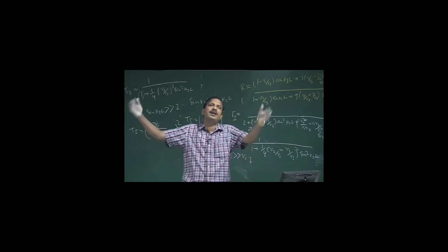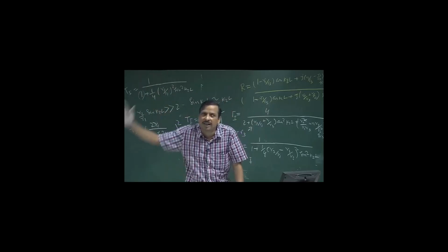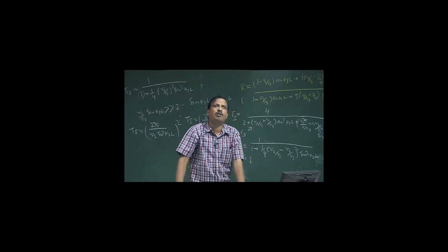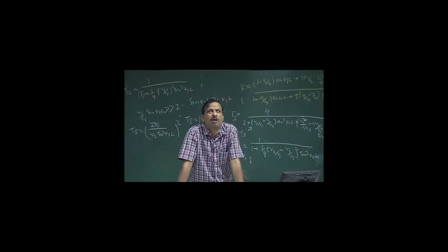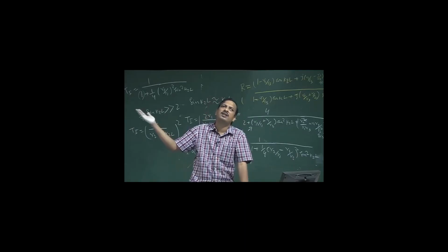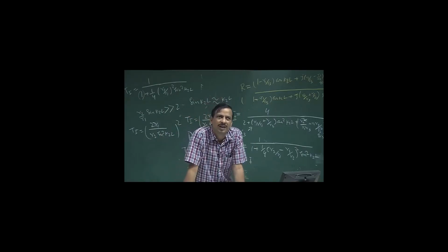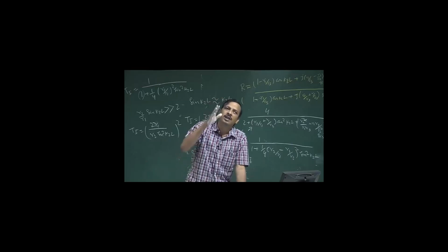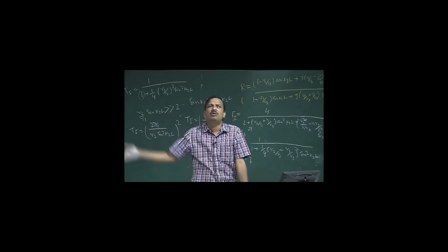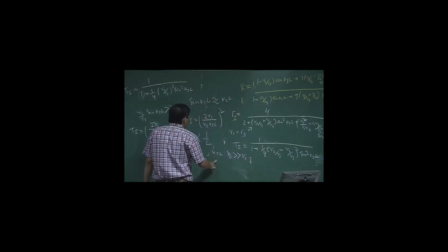So, suppose I want to build a studio or auditorium. If I do not want outside sound to go inside that auditorium, the thickness of the wall of the auditorium must be larger. Okay. So, if the thickness increases, the intensity of the outside sound entering the auditorium will be less. Similarly, the sound inside the auditorium going outside will be very less. So, the thickness of the wall is inversely proportional to the transmitted pressure amplitude.